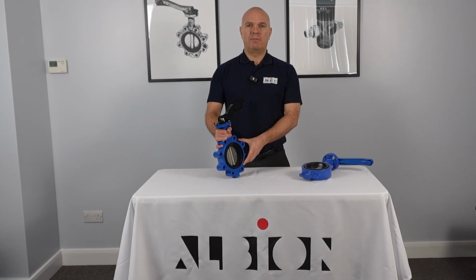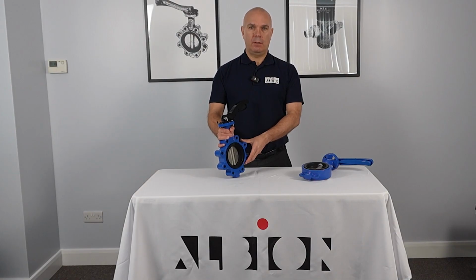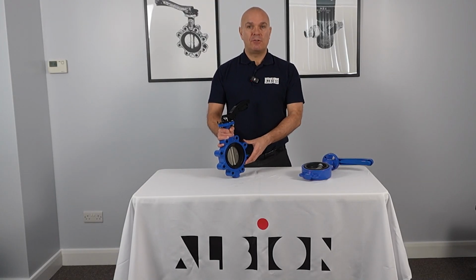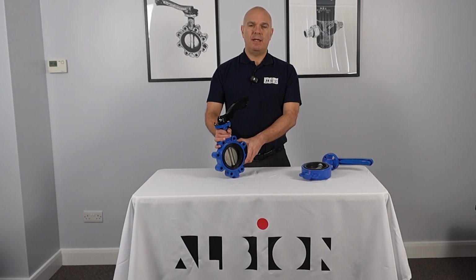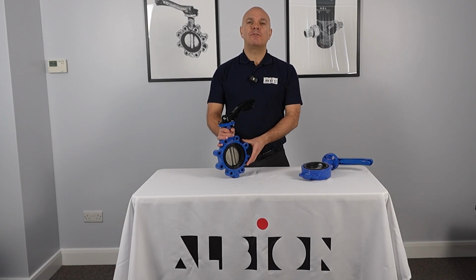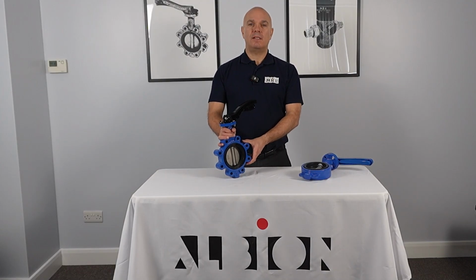The valve disc of a butterfly valve rotates through 90 degrees to control the flow of fluid, gas or slurries through a pipe. When the disc is perpendicular to the flow or fully closed, it blocks it completely. When parallel or fully open, it allows the maximum flow. By positioning the disc at an angle between 0 and 90 degrees, it can be used to throttle or regulate the flow. Any information that is needed regarding flow rates for butterfly valves at any given position can be found either on our website or via Albion's internal technical team.